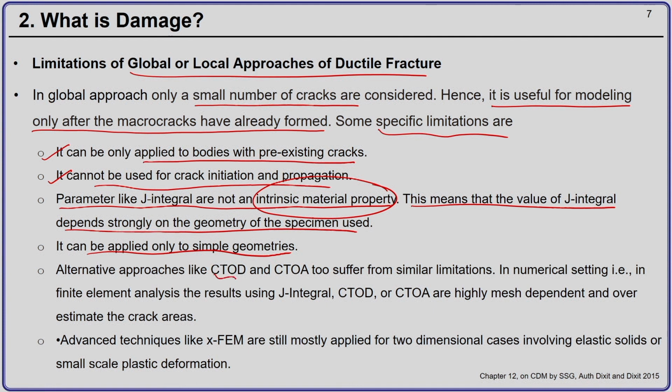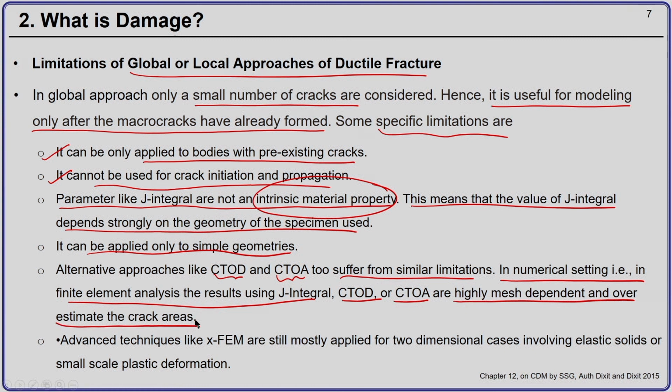Now, alternative approaches like crack tip opening displacement or crack tip opening angle also suffer from similar limitations. In the numerical setting, in finite element analysis, the results using J integral, CTOD, CTOA are highly mesh dependent and overestimate the crack areas. Now, there are advanced techniques like XFEM that are still mostly used for two-dimensional cases involving elastic solids or small scale plastic deformation.